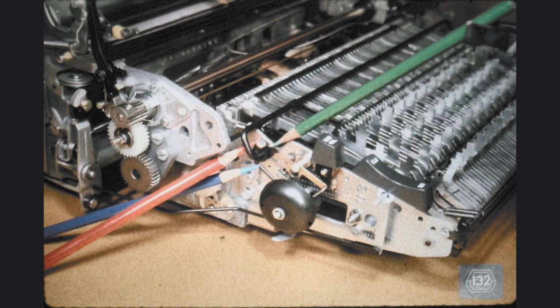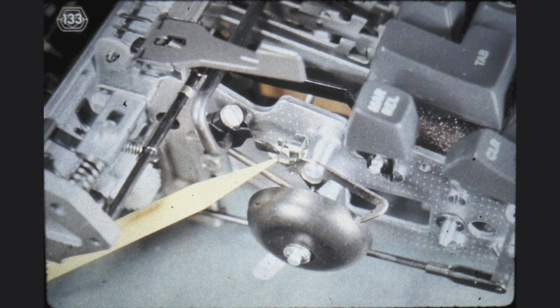The bell is rung by the action of the bell bail lever, at the green pencil, onto the bell hammer. By loosening the screw indicated by the red pencil, it is possible to change the lateral and angular position of the bail lever. Notice that the bell ringer bail is kept rotated top to the rear by the action of the spring indicated by the blue pencil. As mentioned earlier, we adjust the angular position of the bail lever so that it acts on the indicated spring, pushing it down and eventually releasing it to allow the ringing of the bell.